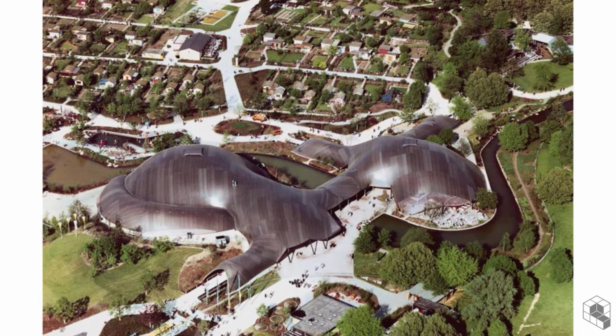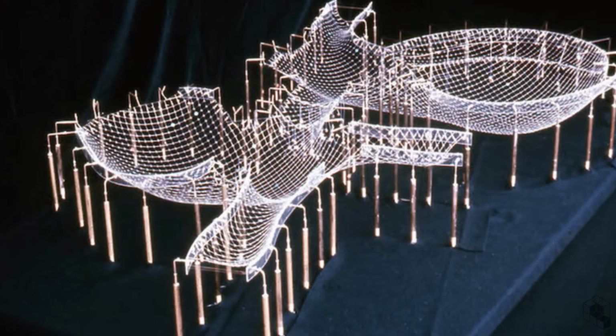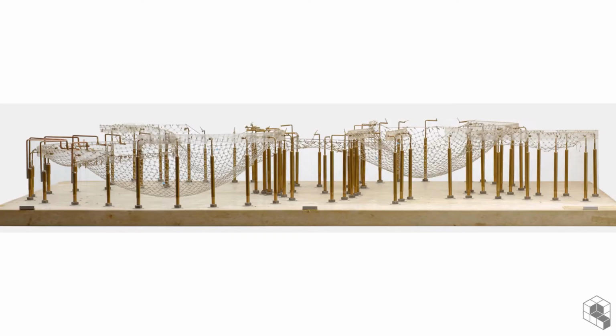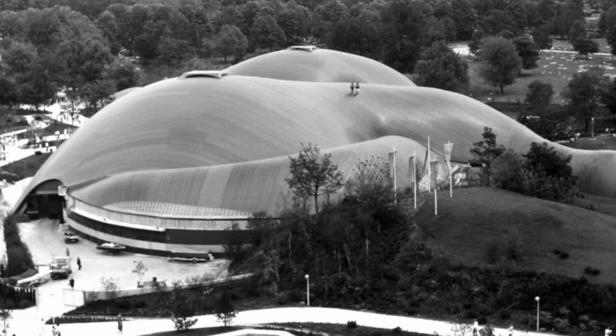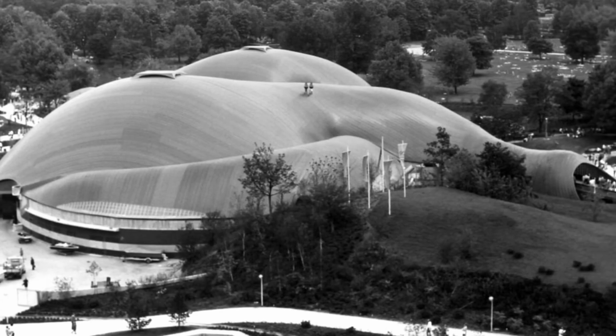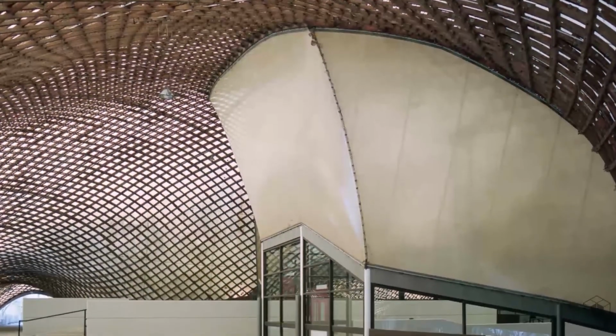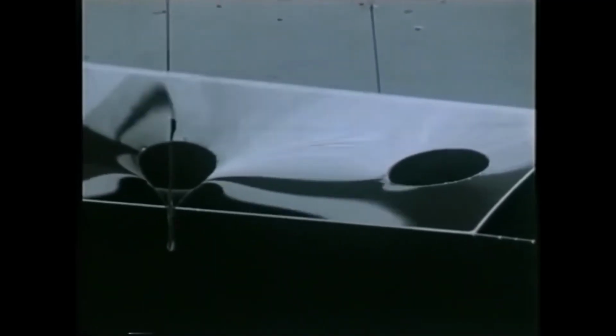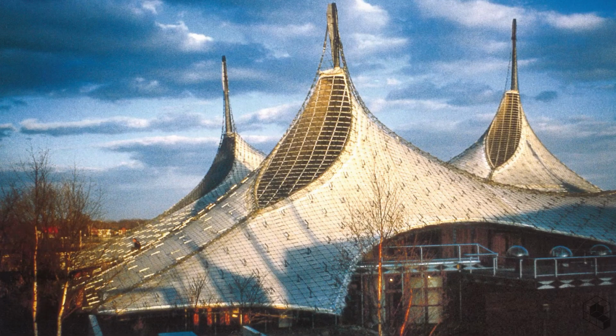Frei Otto, another architect and engineer, took the same principle further and used it to find the structural form of reinforced concrete and masonry vaults, shells, and steel or timber grid shells. His technique takes advantage of non-rigid nets under gravity, custom loads, and fixed boundary conditions for form finding. The Multihalle in Mannheim is probably the most recognized building designed with this method. Other form-finding experiments, such as stretched membranes under pressure and soap bubble models, led to notable projects like the German Pavilion at Expo 67 and the design for the Stuttgart Station proposal.